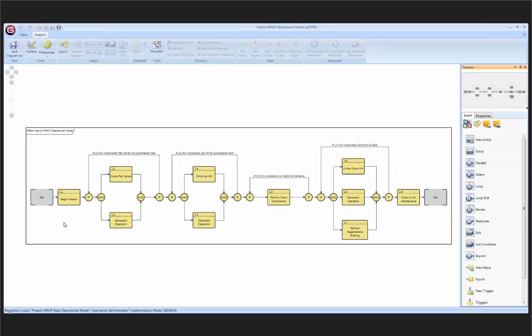What's happening here is I'm going to begin the mission, and as I go on this mission, I have to drive on flat terrain for a certain amount of time, and I'm doing it in 15-minute time increments. When I go uphill on this mission, I'm going to climb uphill, and while I'm climbing, obviously I'm using more battery energy, and the generator is still operating, but it's not going to be able to charge the battery as fast.